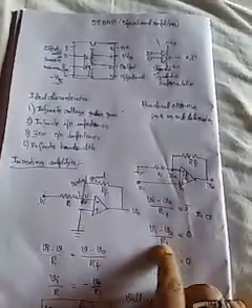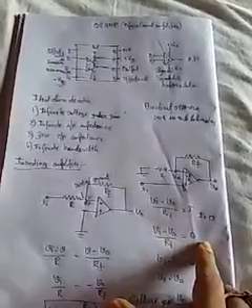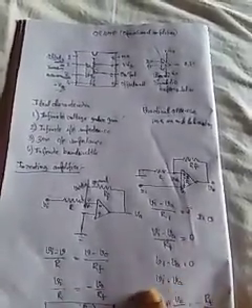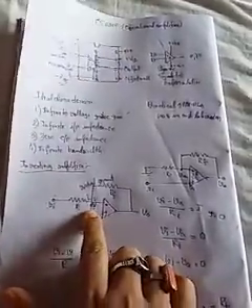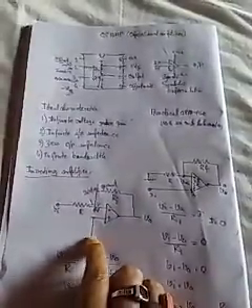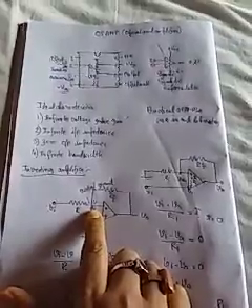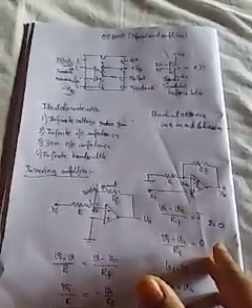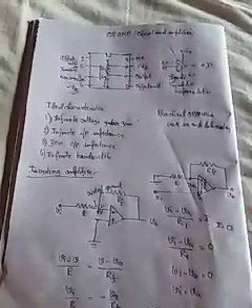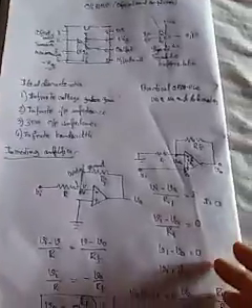So (Vi minus Va) by R1 equals 0, so Vi minus Va equals 0, and this reduces to Vi equals Va. That's why if I apply 0 volts here, it is also applied here. This is the answer to the question of why we choose these two terminals at the same potential. The answer should be written in this way.